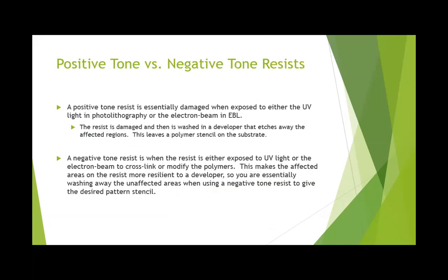But what I just talked about was positive tone versus negative tone resist. A positive tone resist is essentially something that's damaged when exposed either to UV in the case of photolithography or the electron beam in EBL.